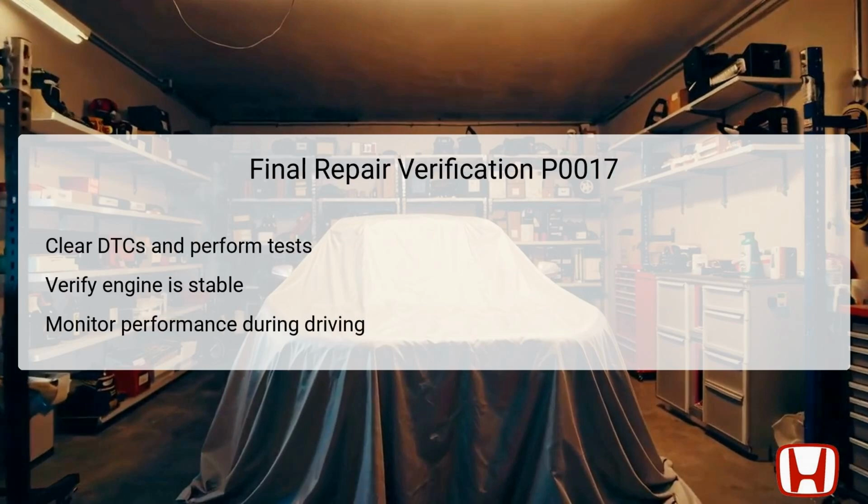Upon completion of the necessary repairs and inspections related to DTC P0017, it's vital to conduct a final verification. Begin by clearing any DTCs stored in the system and reperforming the diagnostic tests to ensure all systems function correctly. After clearing, start the engine and confirm that it runs stable without any irregularities.